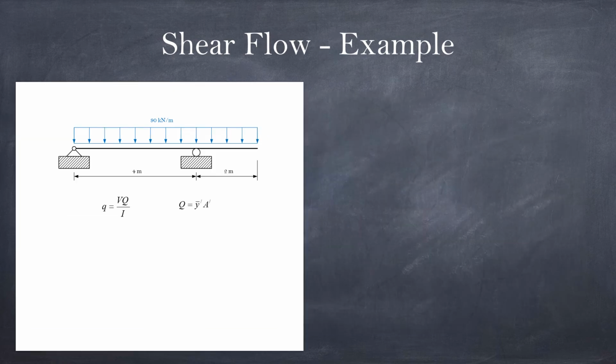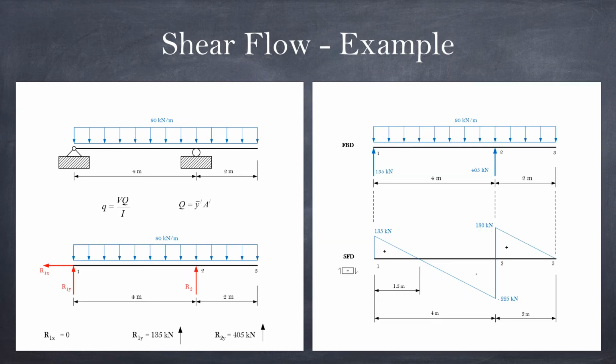Of course, before we can do anything to resist shear flow, we need to know the amount of shear force we need to resist first, right? So the first step is to calculate those first. And to calculate the shear flow, we need to calculate the shear force, the first moment of area, and the value of the area moment of inertia, I, right? So let's go bit by bit. But this one we have seen already on how we calculate the shear.